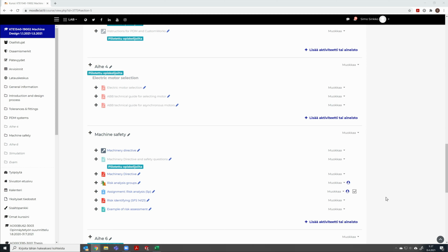About that problem, I think the other student had the same problem, and he found the solution. The section view does not work if you activate the SW settings. So in order to make a section view, you have to sign out from your account and sign in again. But this time, do not activate the SW settings, just open up the file and insert the section view.